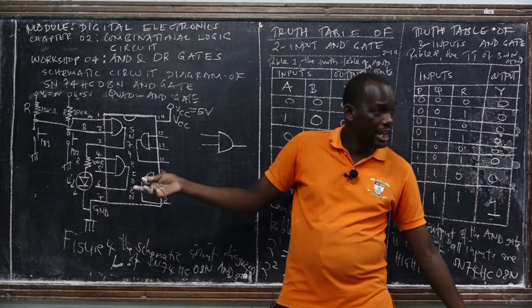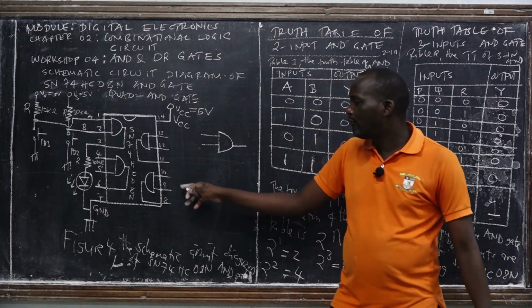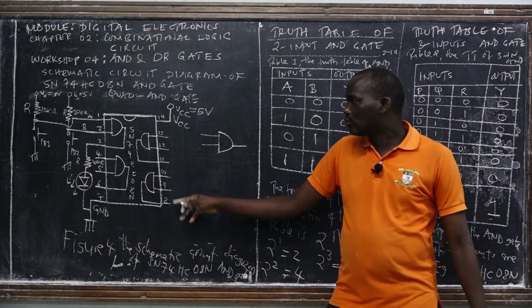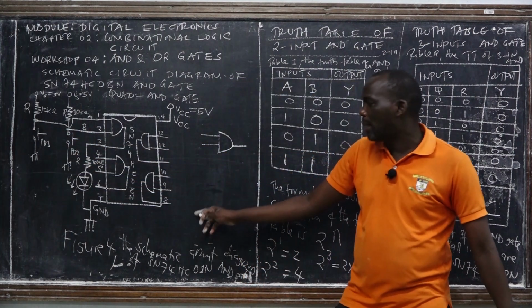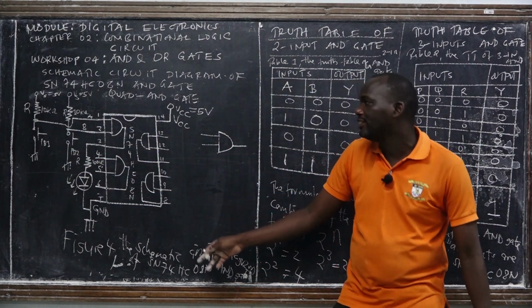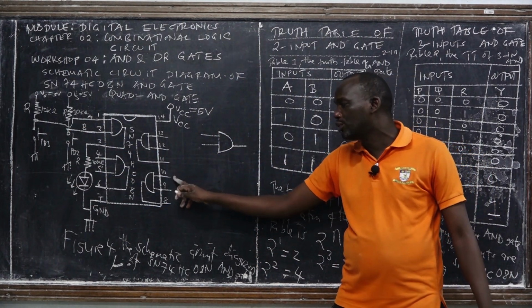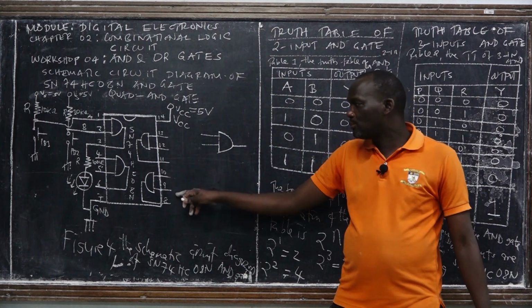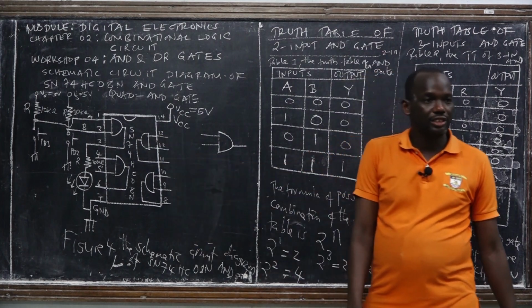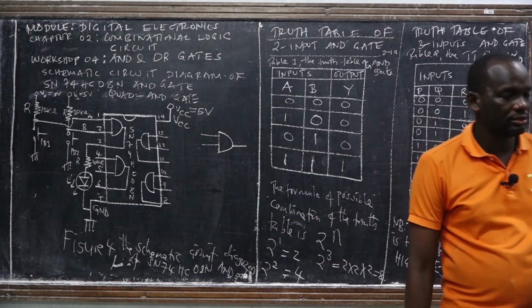Okay? In case you want to use the third AND gate, you just connect the input of pull-up resistor network number 1 to pin number 9, and you connect the input from pull-up resistor number 2 to pin number 10. The same story for AND gate number 4, or the first AND gate.